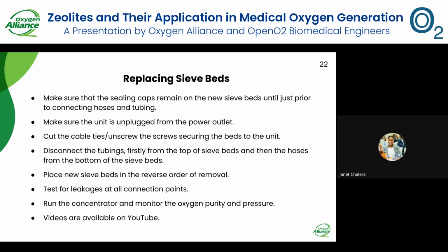Lastly, you have to run the concentrator and monitor the oxygen purity and pressure and make sure that it is within the right range. And furthermore, on the replacement of sieve beds, we actually have videos on the Oxygen Alliance YouTube channel. You can visit the channel to learn more about replacing sieve beds.